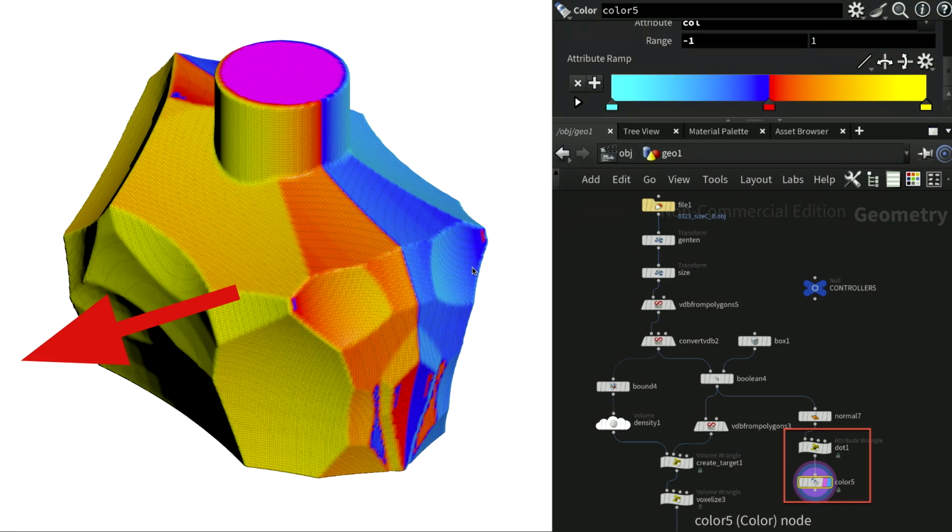So after finalizing the geometry, I analyzed the design in Houdini to check whether it was suitable for molding, using the technique that I showed you. The key aspect of this analysis was to determine the best seam line for splitting the mold. I used simple functions to evaluate whether the mold removal directions were appropriate for the design. From this analysis, we found that keeping the mold seam line as straight as possible was the most effective solution when you actually create a physical mold object.